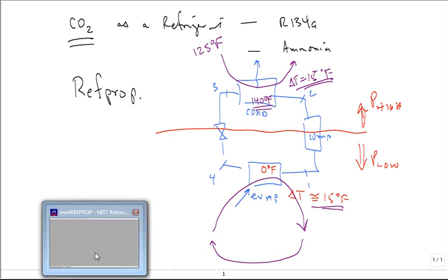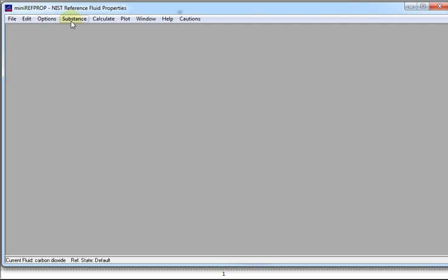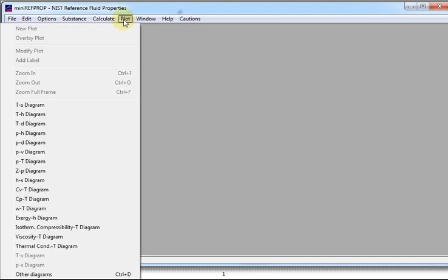Let's jump into here now. We know we're going to work in degrees F, PSI, BTUs per pound, but what type of plot would you like to do to explore CO2 as refrigerant? Temperature entropy, temperature enthalpy, pressure, what is D, density? No, yeah, that's probably density, or PV type of plot, pH, pressure density, pressure specific volume, pressure temperature, ZP. Boy, I'd have to go and look at exactly what type of plot they have. Is that the compressibility factor, Z? Maybe. Okay, I haven't plotted all these.